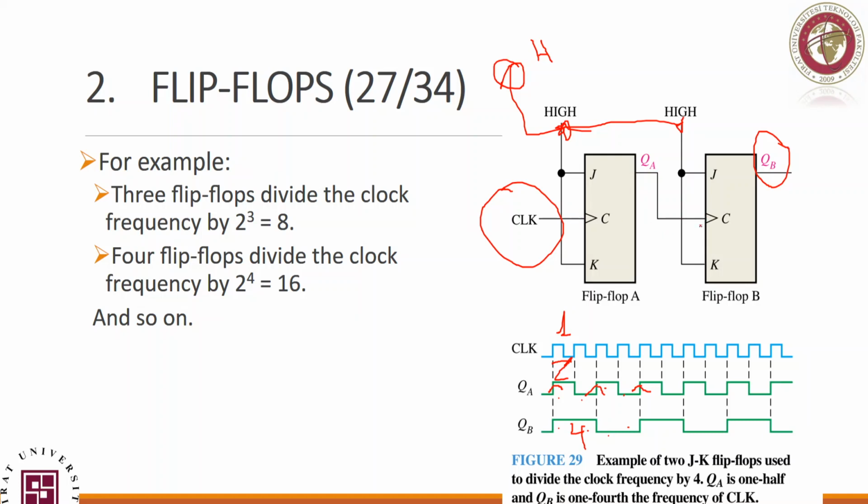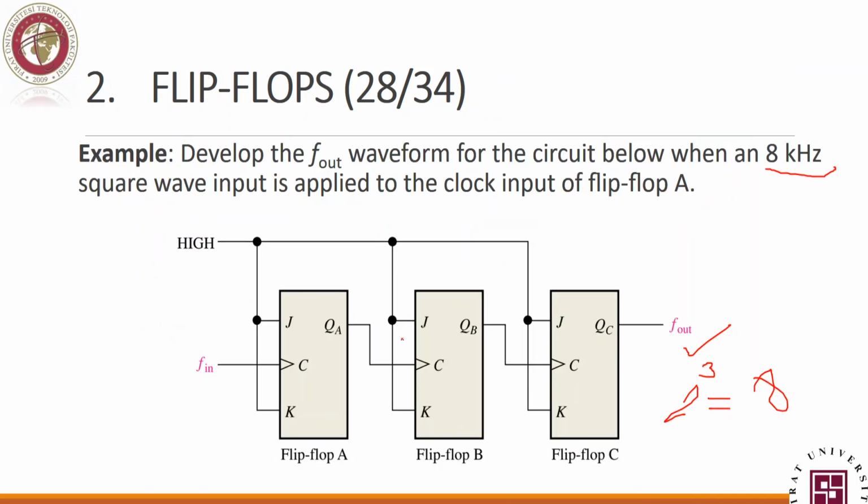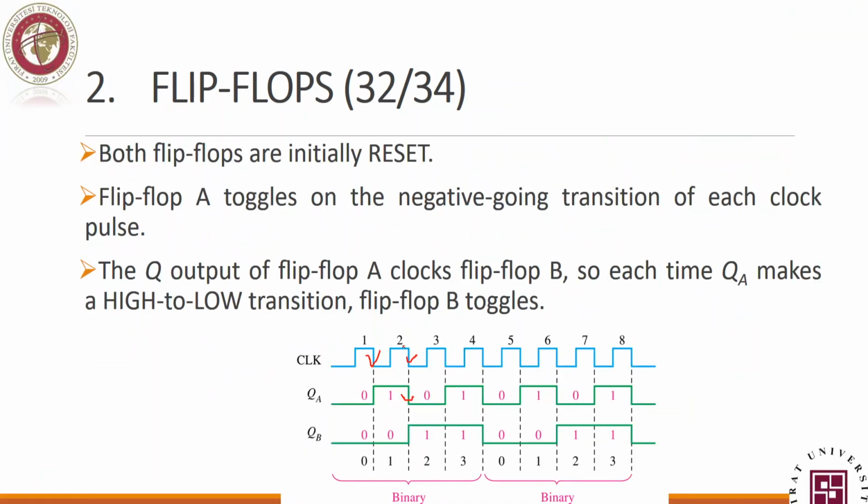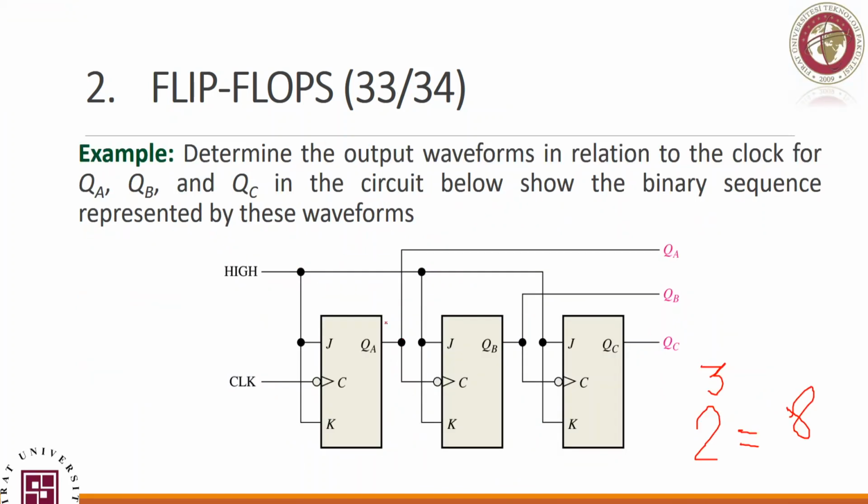And when we invert the clock here, what will happen? We will activate at the falling edge, and that will go from 0, 0, 0, 1, 1, 0, 1, 1, opposite to this, not backwards. Okay? So that was an important point to highlight. In this case we have the bubble, the inversion, which means activation at the falling edge. So we have a forward counter. Forward means we go from 0 to 1, 2, 3, 4, 5, 6, 7. Why 7? Because 2 to the power 3 is 8, so we count from 0 to 7. 0 to 7 means 8 decimal numbers.